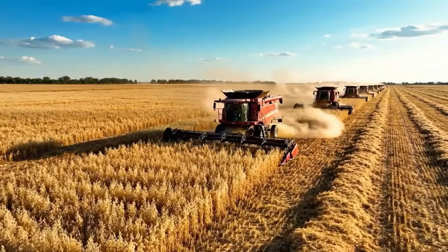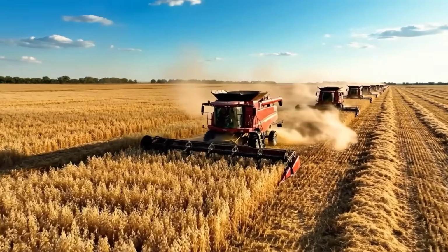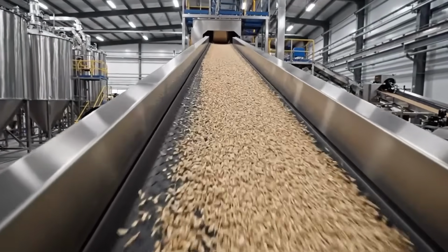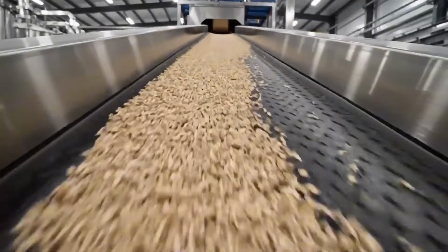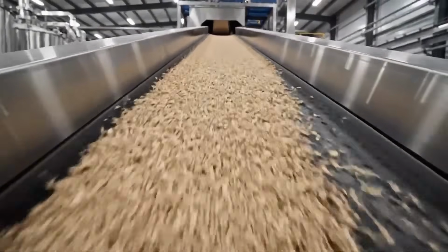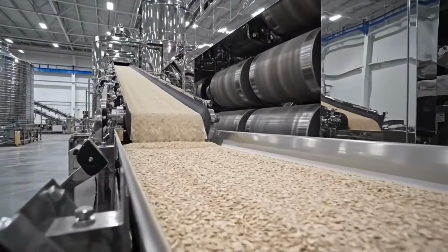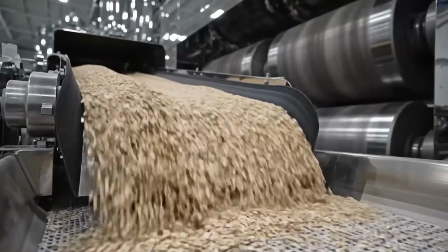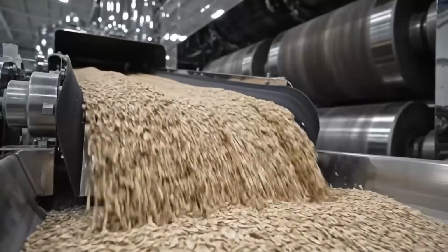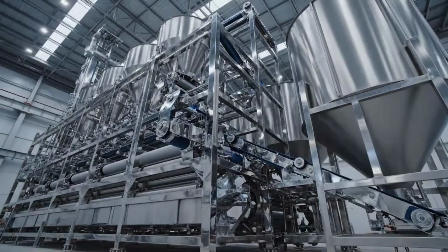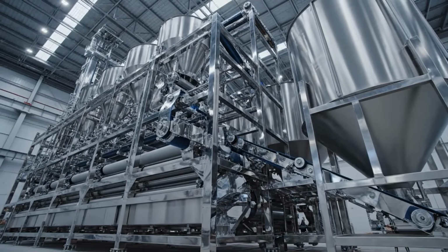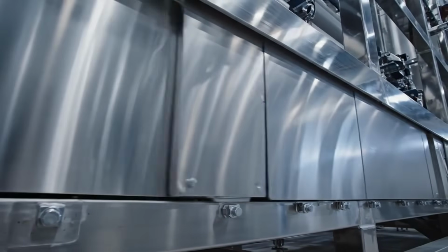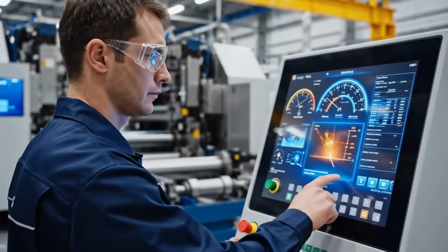Rolled oats are screened to remove fines and oversized flakes. Fines create dust and can make bars dense and crumbly. Oversized flakes create weak points and poor cut edges. If the product uses oat flour or milled oats, that stream is prepared separately and sieved to prevent clumps. Nuts, seeds, or crisp inclusions are sized and cleaned so they do not introduce hard fragments that damage cutters.